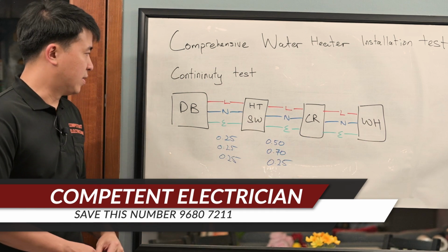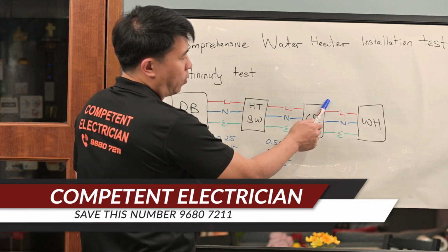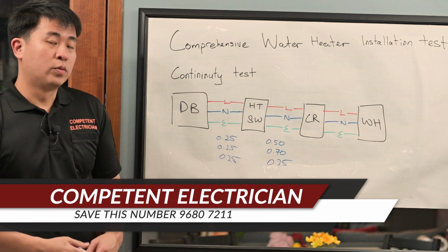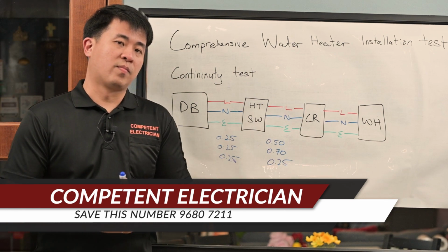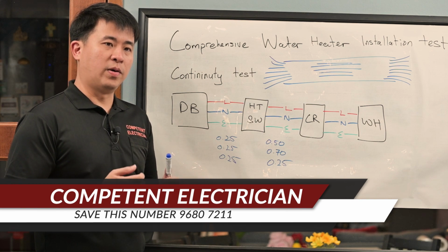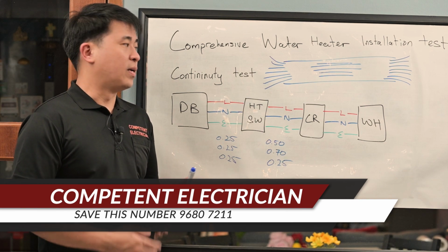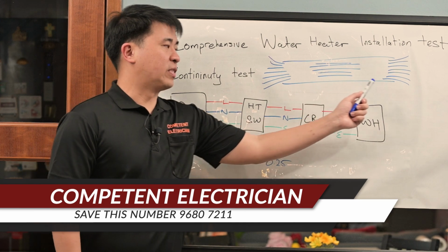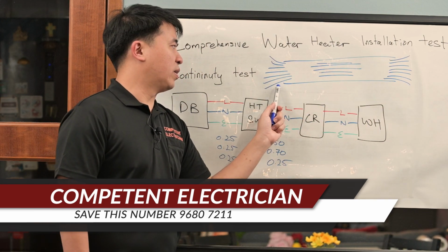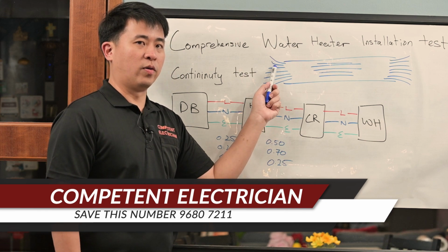We also discovered that most owners use an undersized cable for the ceiling rose connected to the water heater switch. This is a real situation that we faced a few days ago, where we attended a customer's house and both sides show 7 strands of wire. This is a PVC wire. When we strip the wire, we can see the individual strands of the conductor.